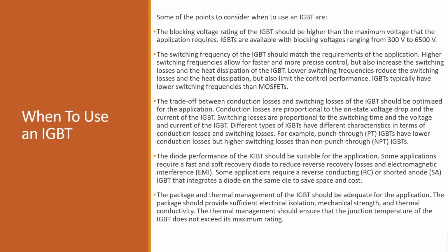The package and thermal management of the IGBT should be adequate for the application. The package should provide sufficient electrical isolation, mechanical strength, and thermal conductivity. The thermal management should ensure that the junction temperature of the IGBT does not exceed its maximum rating.